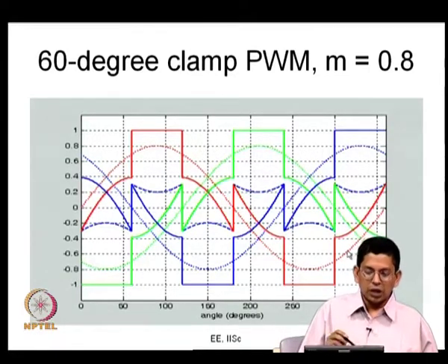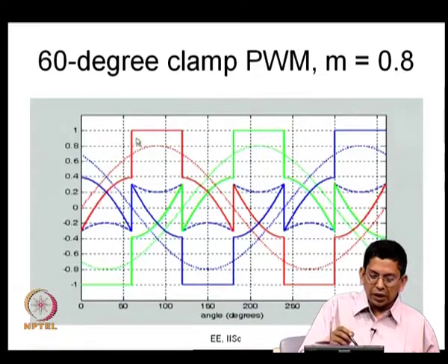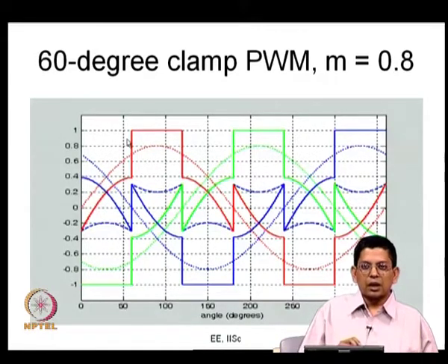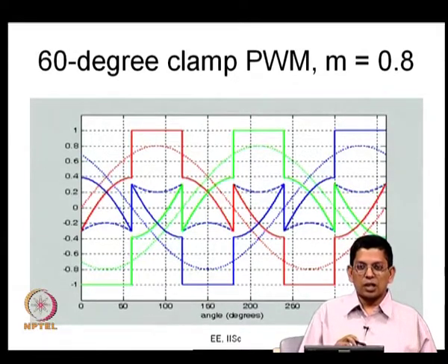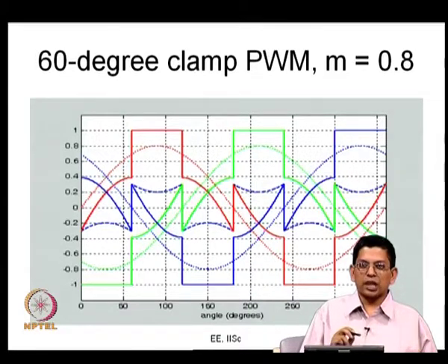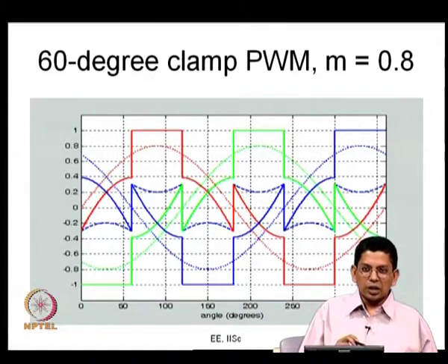So, what happens when the current is close to its peak, the phase is not switching. Every time you turn on and turn off a device, there is going to be loss. And what does that loss depend on? One thing it depends on is the DC bus voltage. It is almost directly proportional to the DC bus voltage, and it is also roughly proportional to the current that is being switched now.